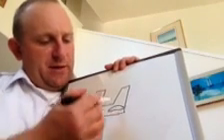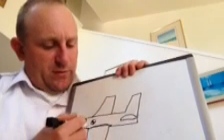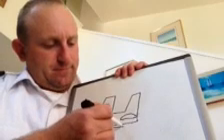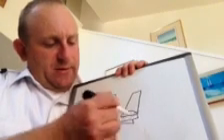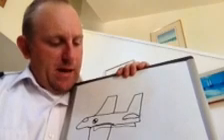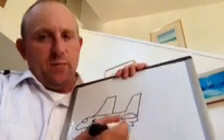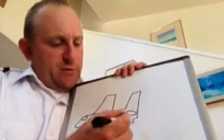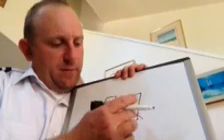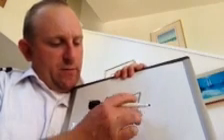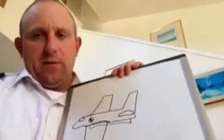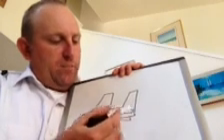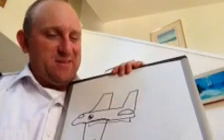Alright, how effective the elevator is, is another thing that we need to cover. Well, the distance that we have from this center of gravity to that elevator is an arm, which is something that we'll probably talk about later in weight and balance. But that arm creates a moment. It creates a force. The further the distance is, the stronger that force is. So any kind of control inputs that we have, with that further distance, they'll be more effective, and that will be more of a force that's created by that arm. There'll be more of a moment, so to speak.